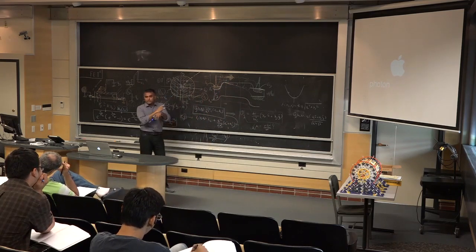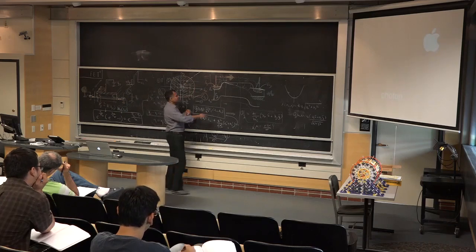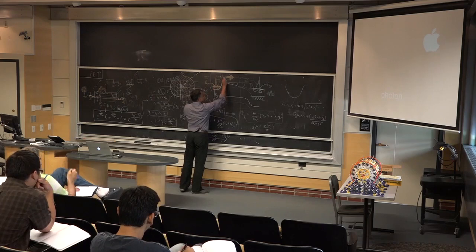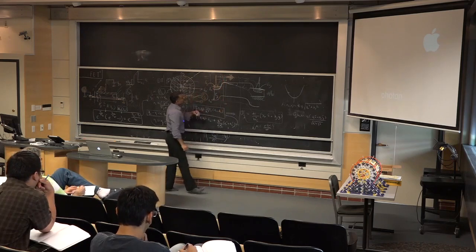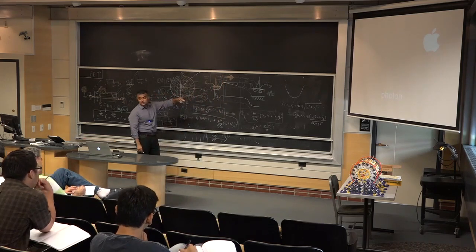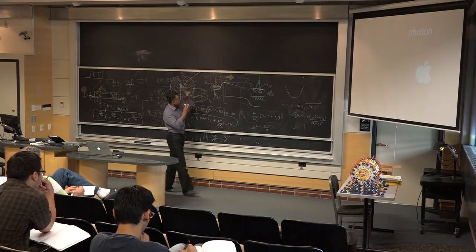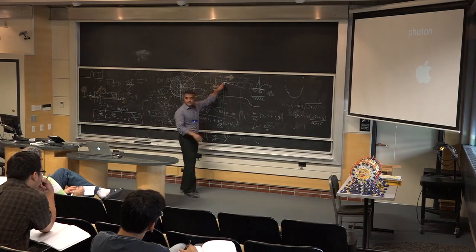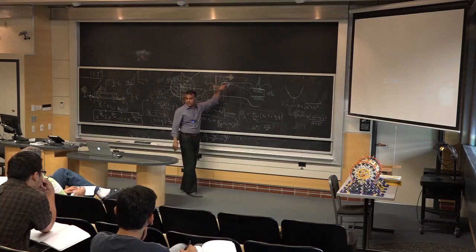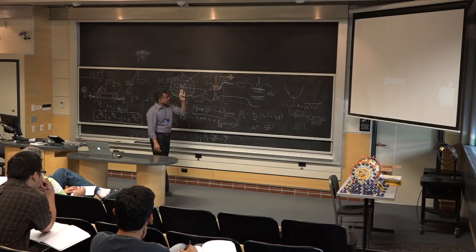So at some point, there is zero slope. At some point, and that's called the top of the barrier. That's one point where the slope of the band diagram is zero. What does that mean? At that point, if you think of it classically, there is no electric field, because electric field is the derivative of the potential, and there is no derivative. It's flat at the top. There's no electric field at that point.